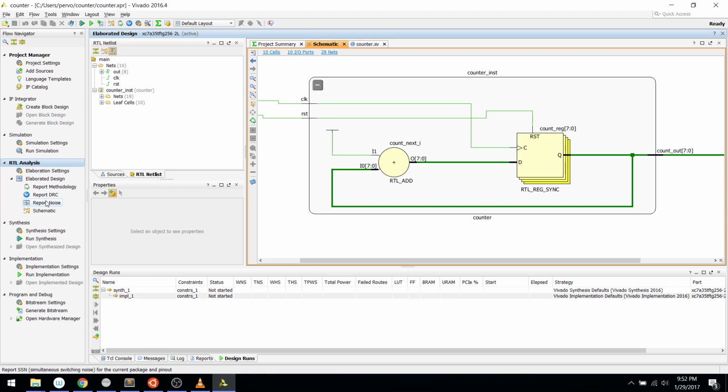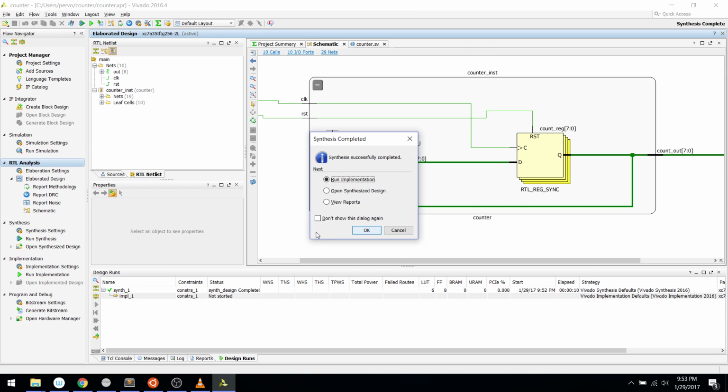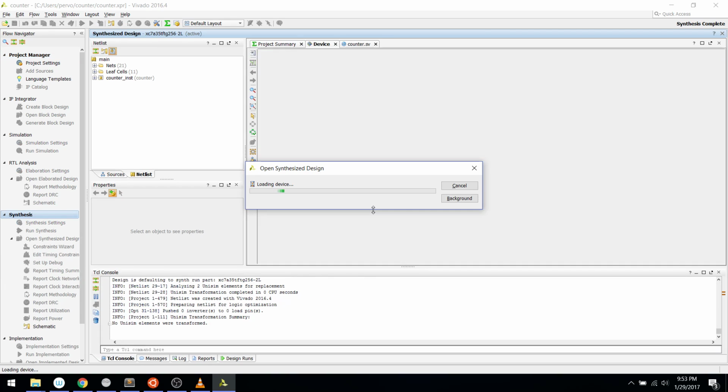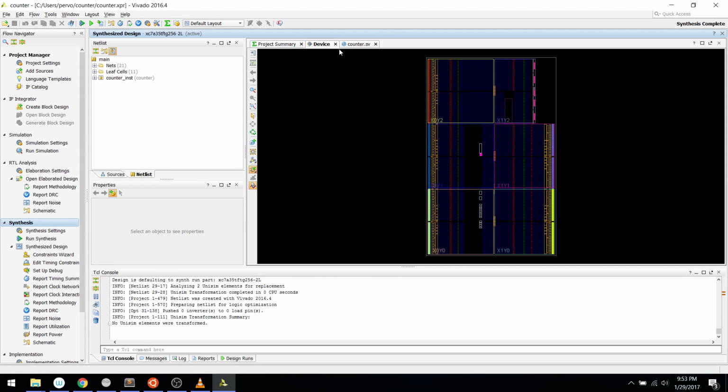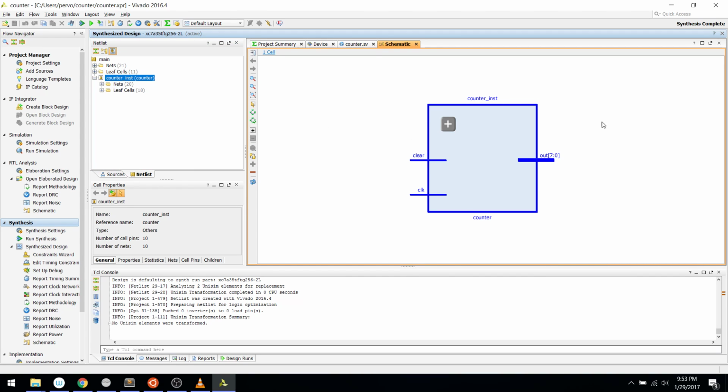And there's some other stuff here we're not going to go into. So next step is synthesis. This is a more in-depth, hardware-specific compilation phase. I don't know if it runs on the elaborated netlist or directly on the source code, because sometimes these are by different vendors. But in any case, you should think of this as doing more vendor-specific, device-specific, hardware-specific compilation. So you can see we've got more nets, we've got a bunch more stuff. If we go to the schematic, this is the same block we were looking at before, but now we're looking at it in the synthesized version.